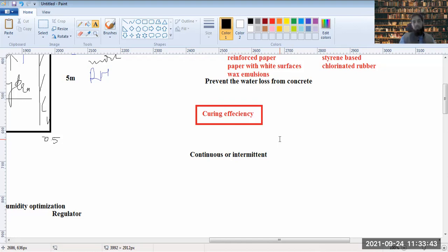In our homes, we construct column structures, and we do not provide the gunny bags. It involves cost. Actually, the cost effect is very less. A gunny bag would cost 50-60 rupees, and even around 100 gunny bags would be 5,000 rupees to the cost of the construction that we usually meet, which is around in lakhs. So keeping 100 gunny bags at our homes, which is 5,000 rupees, is not a huge cost. But still, we do not focus on curing because people do not have knowledge about how important is curing and the length of the curing.